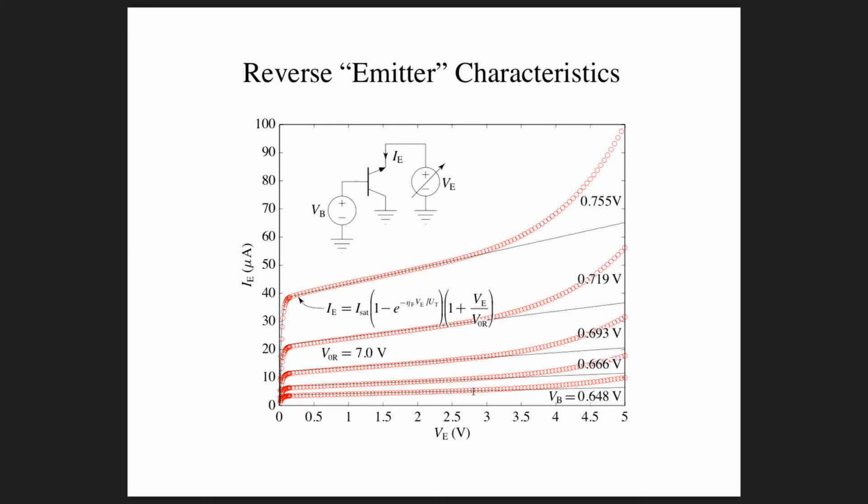But once we get up above maybe 2.5 volts, close to 3 volts, we start to get some curvature in these curves, and they start to take off. This is the start of the so-called breakdown of the transistor, where if you take the voltage across the device high enough, the transistor actually breaks down. The 2 depletion regions around the base emitter junction and the base collector junction touch each other, and you basically get a short circuit through the device instead of the normal transistor action.